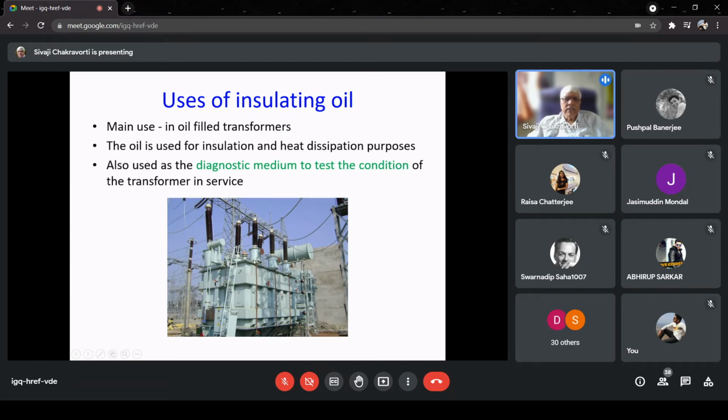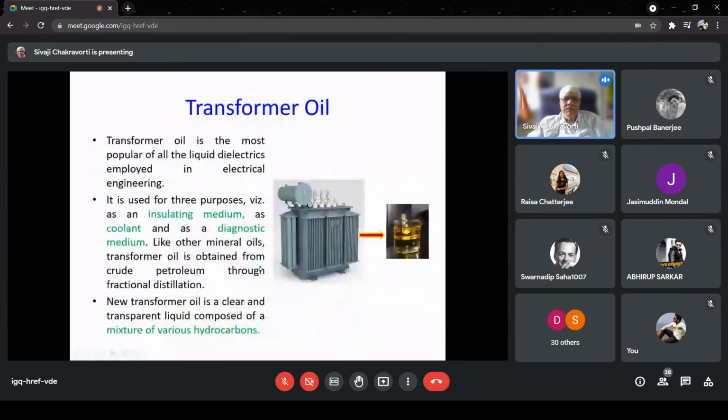So, the tank cover is metal, the tank top surface is metal, and we cannot put one on top of the other. So what we do is put something called a gasket in between, which is, by the way, an insulating material. And that gasket can be compressed, and that's how it is sealed. But that sealing somewhere can become bad and moisture can go in. So there are many other ways that moisture can go in.